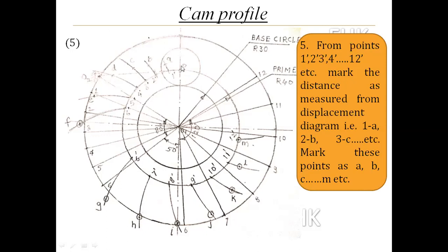Okay. Now, whatever points you are getting here, A, B, these are not the points of tangency through which you have to draw the curvature. These are the centers of the roller. Understand that point: these A, B, C, D are the centers of the roller. So A as a center, draw the roller position. B as a center, draw the roller, which is 10 mm radius.